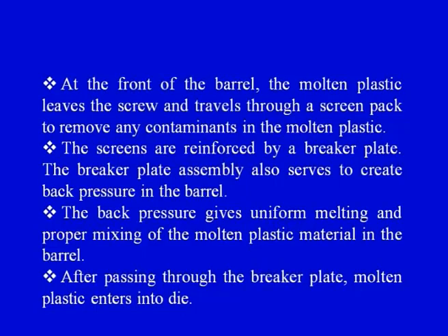Now, the screens are reinforced by a breaker plate. The breaker plate assembly also serves to create the back pressure in the barrel. The back pressure gives uniform melting and proper mixing of the molten plastic material in the barrel. After passing through the breaker plate, molten plastic enters into the die. Now, the final stage is where the material has to be formed.